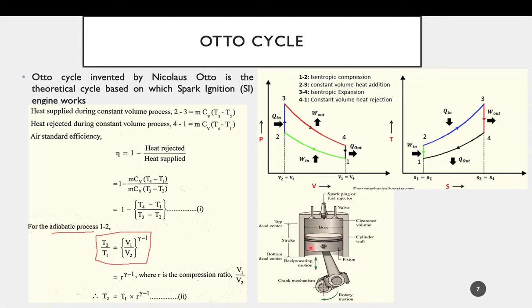Now the volume that is sucked by the cylinder, that is the volume between the top dead center and bottom dead center, is known as the sucked volume. So total volume is the sum of clearance volume and sucked volume. I hope that is clear. So we now know what total volume and clearance volume are. Total volume is the volume from the bottom surface of the cylinder to the top surface of the piston when the piston is at bottom dead center. If we consider the PV diagram, the total volume will be the volume from the origin to the bottom dead center, that is state point 1, because the piston will move up to this one.